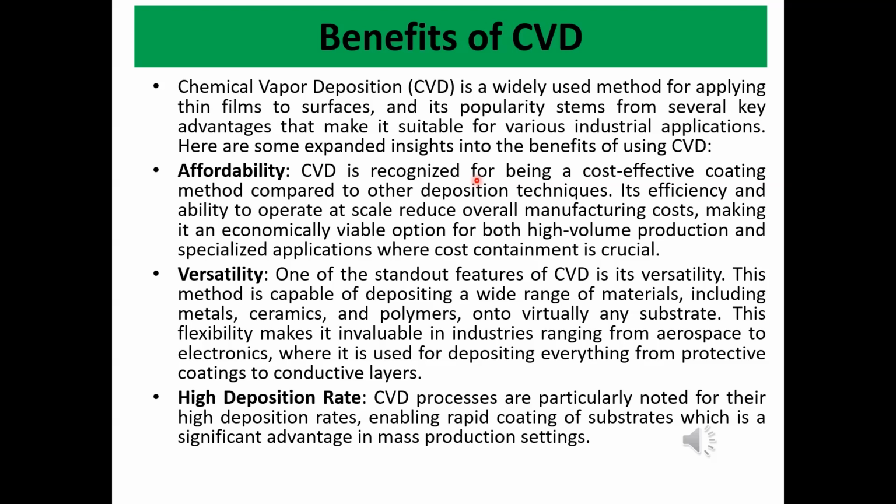At the same time, using the chemical vapor deposition technique, we can deposit thin films of silicon carbide at a comparatively lower temperature. So, based on this fact, we may say that CVD is a technique which is more economic and affordable as compared to the other relevant techniques.